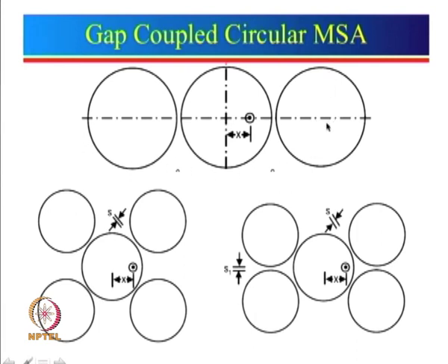The results are very similar to the radiating edge gap coupled, we could get a broader bandwidth as well as higher gain. Now, for the non radiating edges, one has to do a little more thinking. One should not just put the patch along the non radiating edge, because the field is 0 here, which goes to plus, right. So, if you put another patch on this side right here, coupling to that patch will be close to 0. So, we found an alternate way by knowing the field distribution.